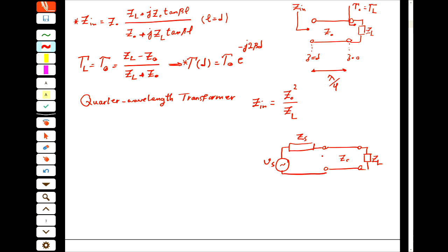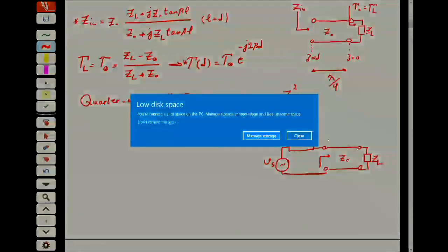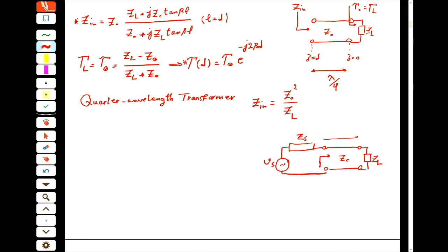And we said that if we look at the impedance of this transmission line connected to the load and assume that the length of this line is, for example, L, and the input impedance at this point is Zin, then the perfect power transfer from your Vs to ZL happens if your Zs is Zin conjugate. So this is what we found.